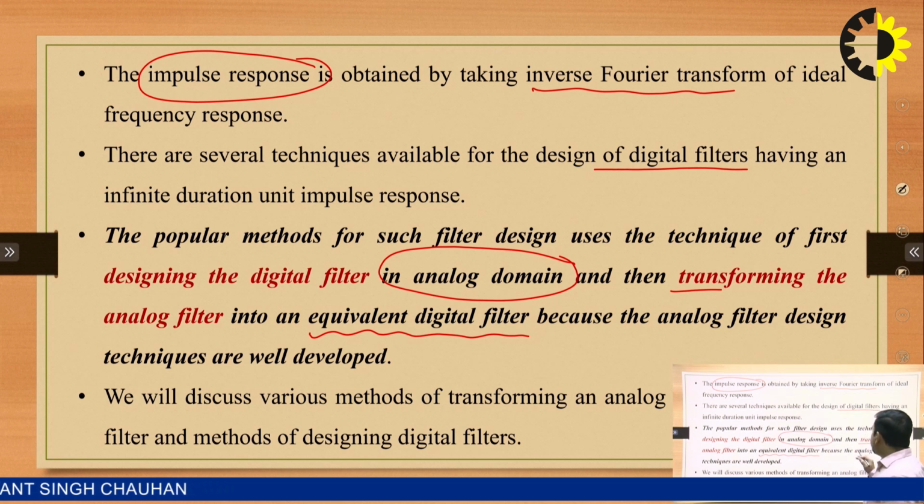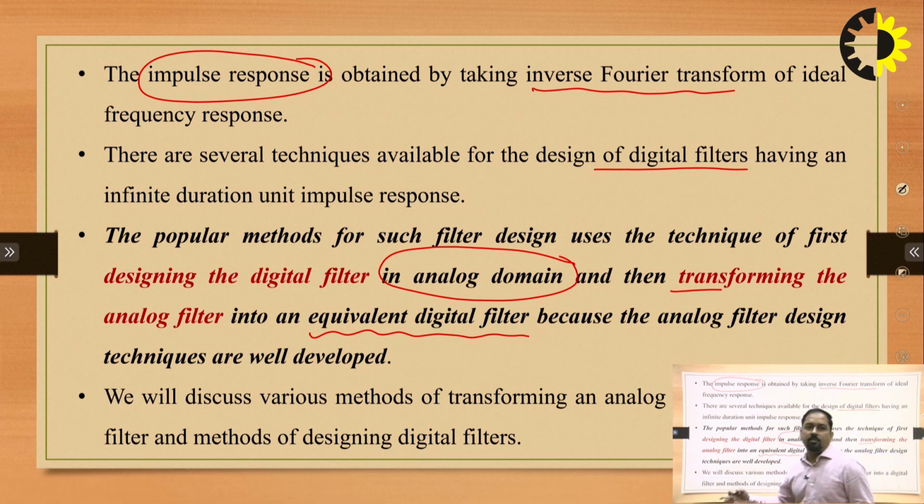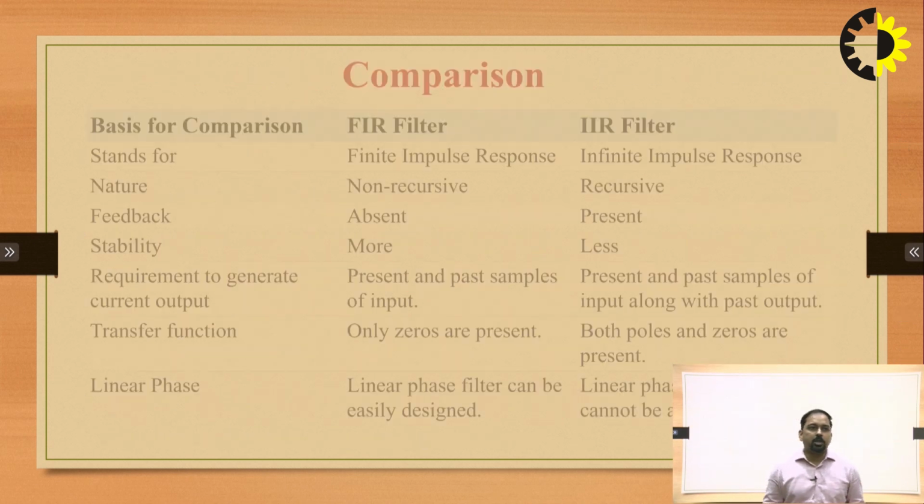because the analog filter design techniques are well developed basically. So later on we'll discuss various methods for transforming an analog filter into a digital filter, and we'll see the method of designing digital filters. So this is the basic theme behind the design of IIR filters. First we'll design an analog filter, and then we'll transform it to the digital domain or the digital filter.